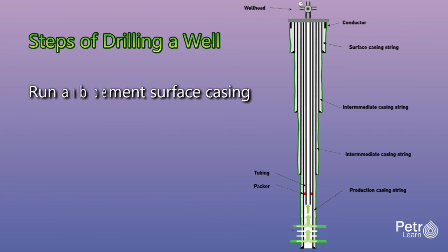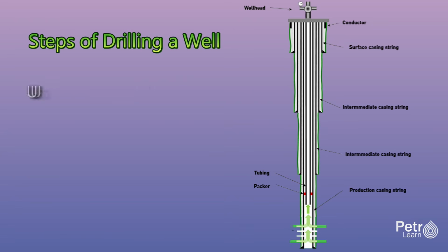Drilling continues until the planned depth for the surface casing is reached. The drill string is stripped out, and the surface casing is run and cemented. Surface casing is typically 13 3/8 inches in diameter, with walls of 0.48 to 0.72 inches thick, depending on the pressure rating needed. This casing string is critical because it isolates and protects all freshwater zones and provides structural support for the well. The cement job must be excellent, with cement circulated all the way to the surface.